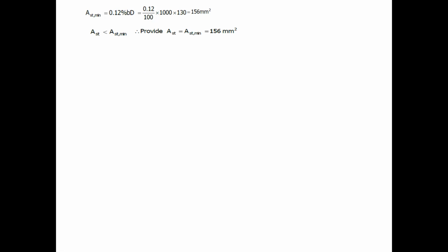Okay. Next, what is the next step after getting Ast? You have to calculate the spacing of the reinforcement. Yes, sir.